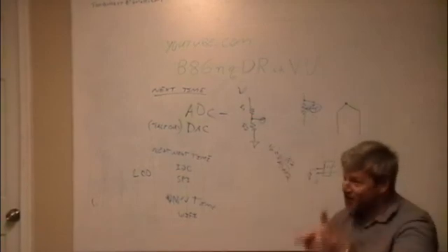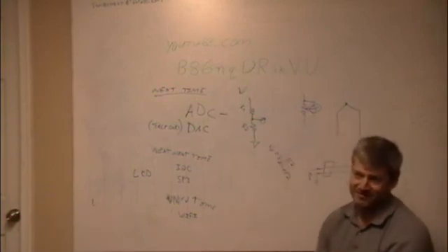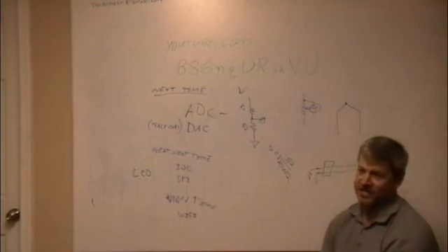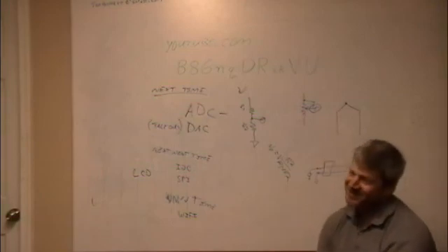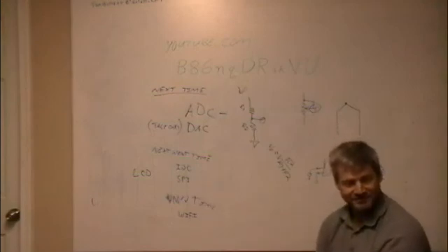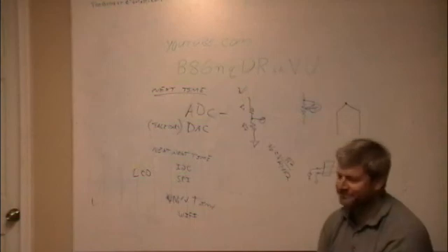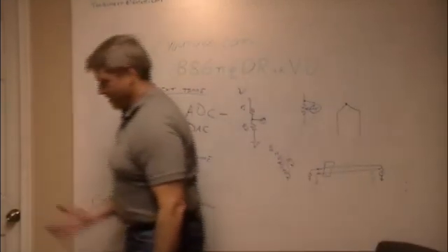So yeah, I've done this before. Mine's simple, right? I've got one thing that I want to control and heat and cool and heat. But now if you get into multiple zones, you're going to spend a lot of time in software writing your PID loop. The loops, because you'll have one for each one, if they're all different. What I was going to say is the firmware for my printer has a PID tuning function where I think it goes full bore and then measures the thermal drop off and figures out what the characteristics are. So anytime you make any kind of change to the hot end of the 3D printer, you just do the PID tuning and it figures out what that curve is for you.